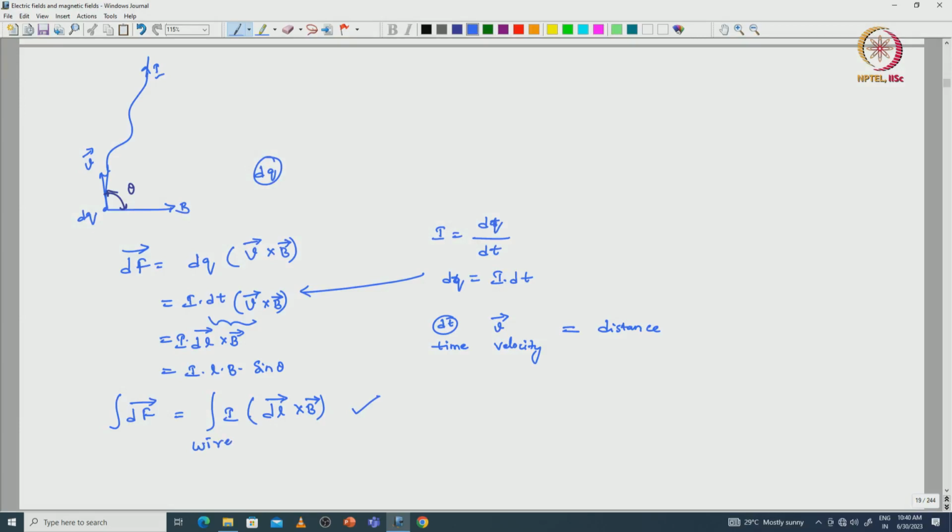Now, we will calculate the torque. Torque is equal to force into the distance between the two current carrying wires, which I am representing with x. The force equation we know and x is the distance, so the final torque equation is B I L X into sin theta.